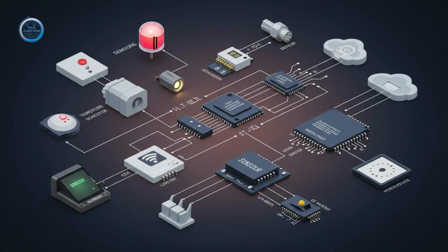And another major one is SPI, the Serial Peripheral Interface. SPI is generally faster than I2C. It typically uses four wires: one for the clock, SCLK; one for master out slave in data, MOSI; one for master in slave out data, MISO; and one for selecting which slave device the master is talking to, slave select or chip select, SS or CS.